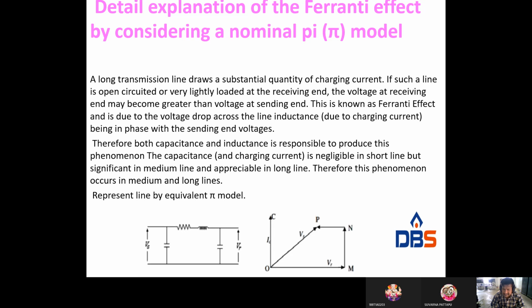Therefore, both capacitance and inductance are responsible for producing this phenomenon. Capacitance, that is the charging current, is negligible in a short transmission line. Why? Because there is no significant capacitance in a short line, but in medium and long lines we have to consider it. Therefore, this phenomenon occurs only in medium and long lines. That's why there is no Ferranti effect in a short transmission line. The Ferranti effect is applicable only to medium and long transmission lines.